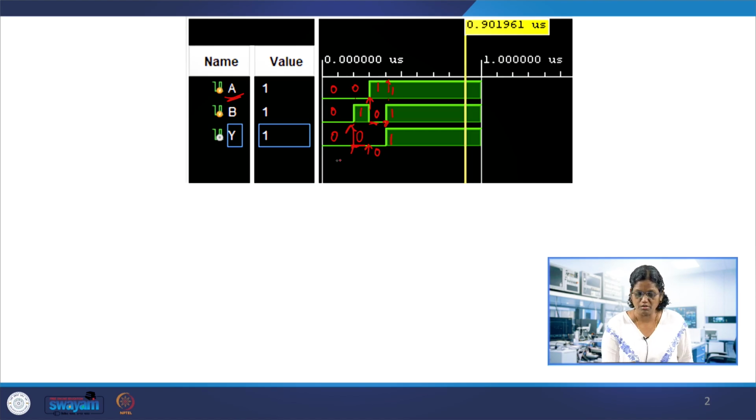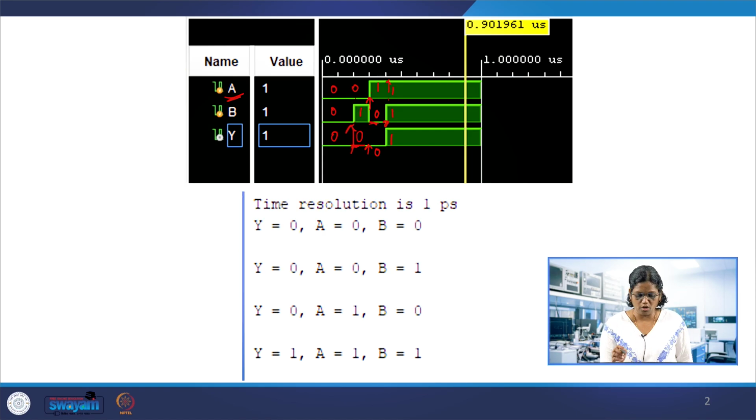You can see the time variations where we are changing the input also. Because A and B are single bit, you see the waveform as 1 bit, how the 1-bit digital 0 and 1 is changing here. So, this is the output of the waveform editor, which is monitored. If you use the $monitor in the Tcl console, there in the design suite or the Vivado environment or in the simulator, the time resolution here is taken as picoseconds, or it can be in nanoseconds as well.